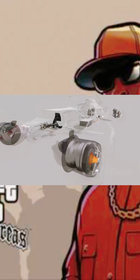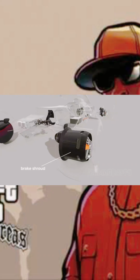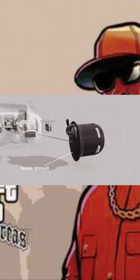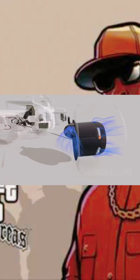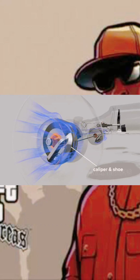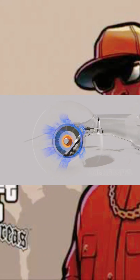The screw position allows different pressure to the front or rear brakes. Brake lines snake through suspension elements to the brake caliper and shoe assembly. Intense brake heat must be precisely managed, so the entire inner wheel assembly is covered by a ducted carbon fiber shroud. The front wing helps direct air into the brake ducts and through the inner wheel for cooling. The calipers are mounted at the lowest possible position for proper brake bleed. That is, ensuring troublesome air bubbles can escape hydraulic brake lines, while maintaining a low center of gravity.